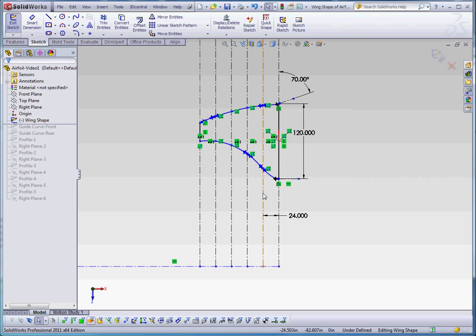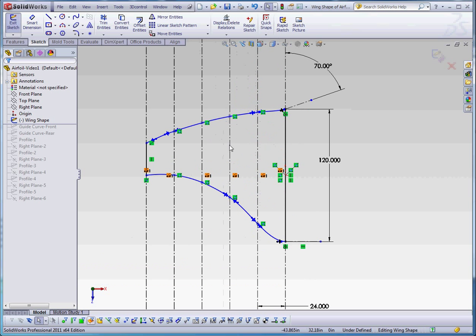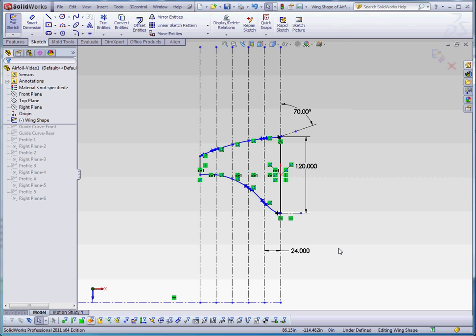So in a way, with not only the outline of the airplane wing that you see in this top sketch, I'm also drawing out where some of the reference geometry for each one of these spar locations are going to be in regard to the profiles I'm going to be using for the loft, if that makes sense. So this is an important sketch. It's a good starting sketch in order to get that geometry in place, and then after that we're going to go ahead and create our planes, and from those planes we're going to draw our profiles in order to get our loft put together.